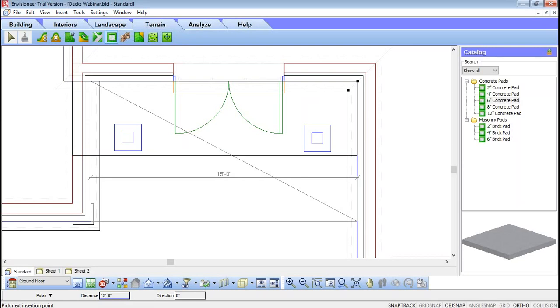I'm going to hover over top of that point. I'm not going to click, but simply hover. I get the black node there, and as I drag away, it might be a little bit tough to see, but you can see a dashed line running vertically on the screen from that reference point that I hovered on. That means I've got a snap track line there, and when I've got that snap track line, I can simply left click and it puts in that point there because I've got my snap track reference.